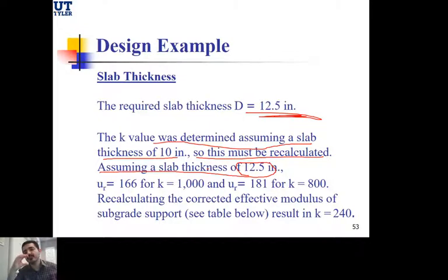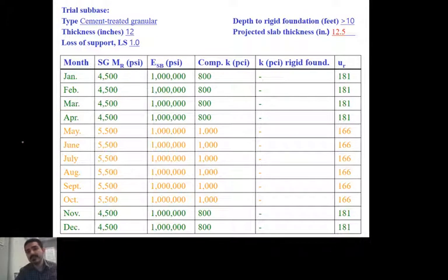But again, if you have that question in mind, yes, when we design the PCC structure, we assume a certain thickness of the PCC layer and a certain thickness of the subbase. The subbase doesn't change, it's going to be fixed, but with the iterations, we need to keep changing the thickness of the PCC layer. So what is this going to impact? It's going to impact only this column right here, because again, you're going to repeat the entire table one more time.